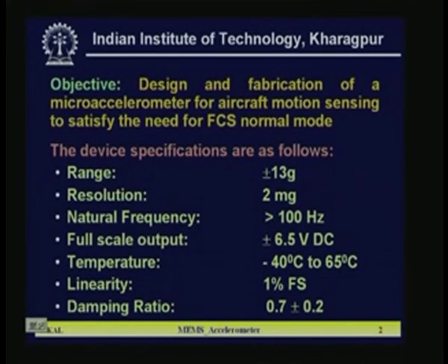Those specifications are highlighted in this slide, recorded from the data required for guiding an aeroplane, that is the flight control system normal mode. For them, specific requirements are resolution, off axis sensitivity, temperature stability, linearity, etc.